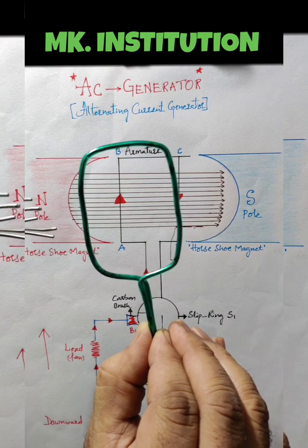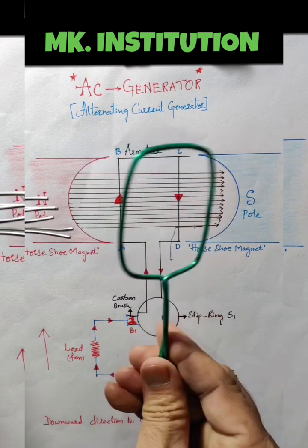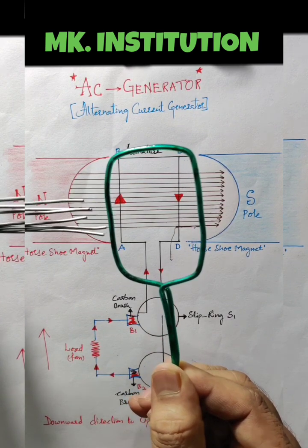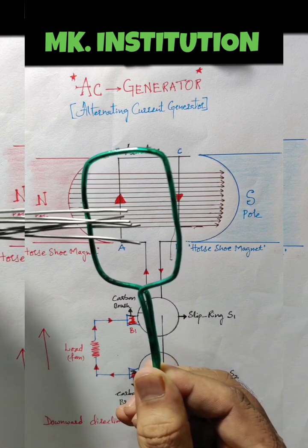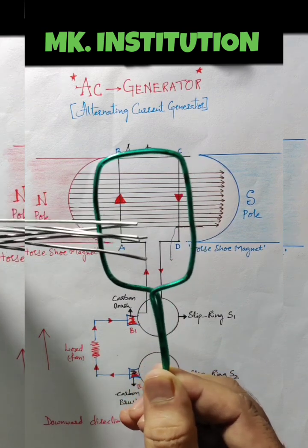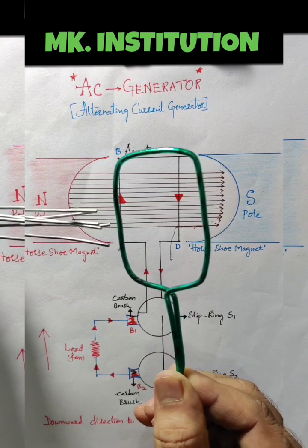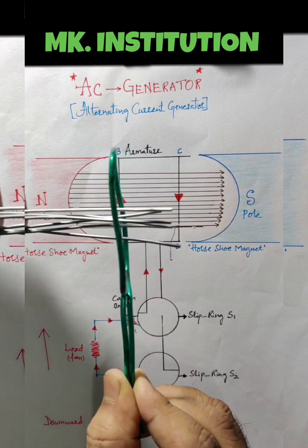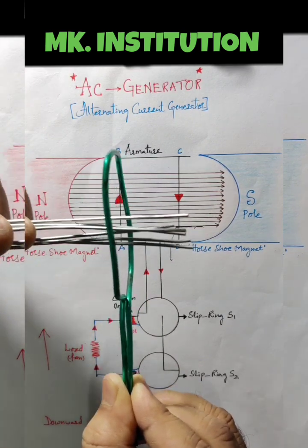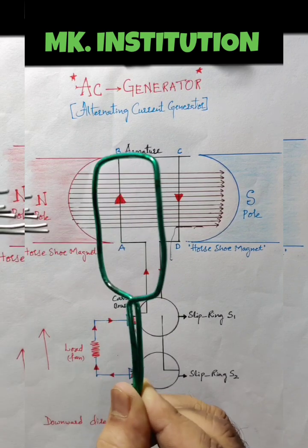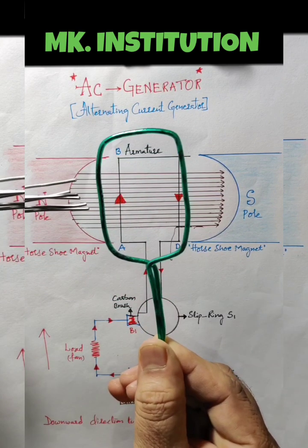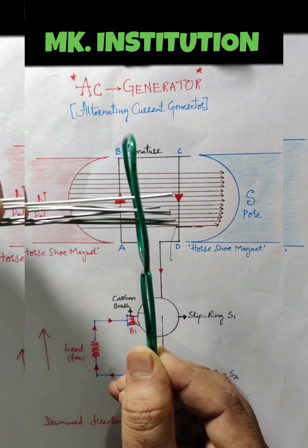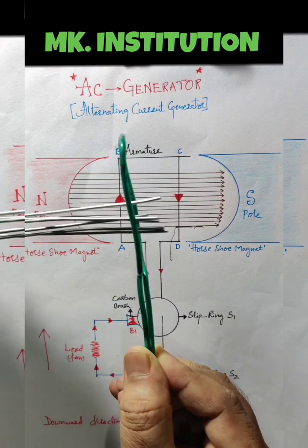But slowly, by the force of this magnetic field, the armature starts moving. When it starts moving, maybe 2 or 3 lines come this side and 4 or 5 go that side, up to 10 on average. While moving, a time comes when the armature will be vertical, and then all the lines can easily get inside. This is a quarter, 1/4. When the armature moves 1/4, it is in the vertical position, and maximum magnetic field lines, 0 to 10, are going here.